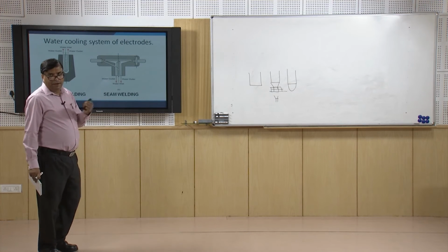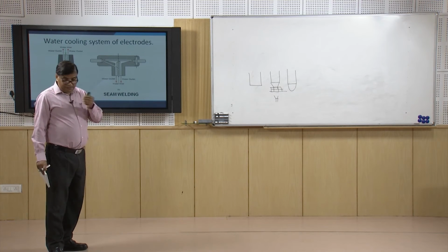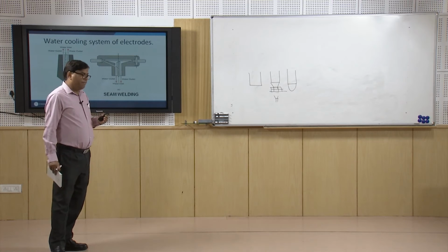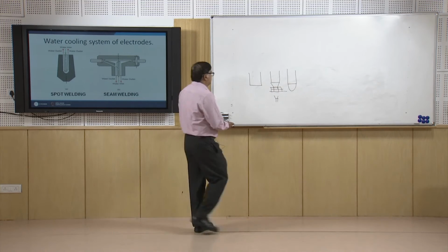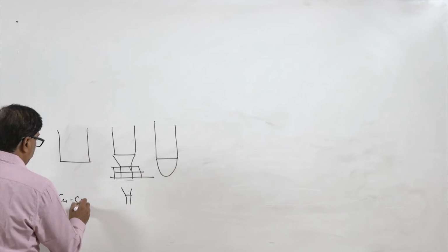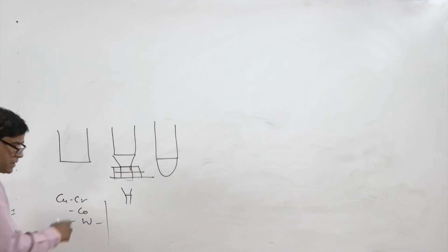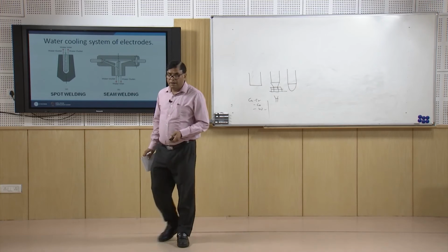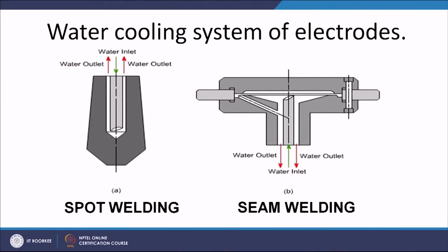made of copper and copper based alloys in order to have reasonably high temperature strength and in order to resist the wear. Normally the alloys of different systems like copper-chromium, copper-cobalt, copper-tungsten, and other mixtures and other alloying elements in the copper are used in order to increase their capability to withstand the higher temperature, but still it is required that the temperature of the electrodes is kept within the safe temperature limits.